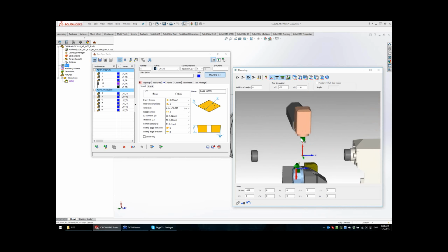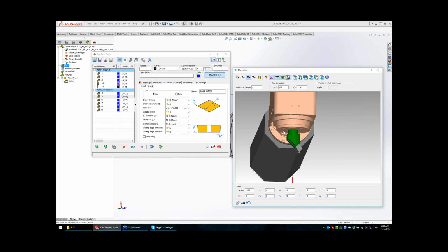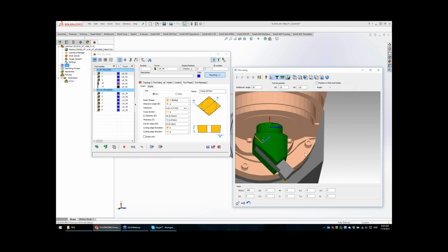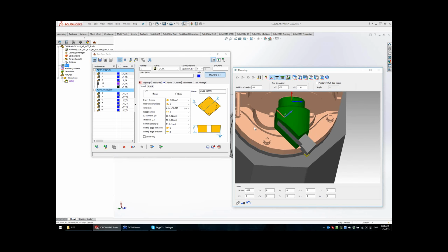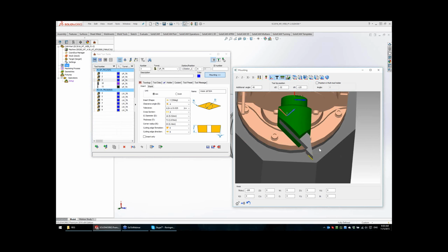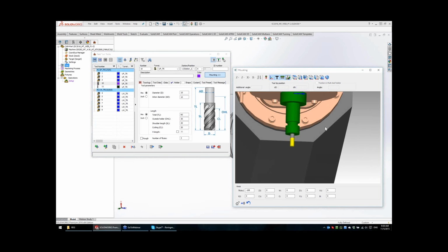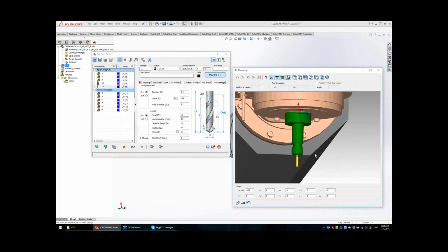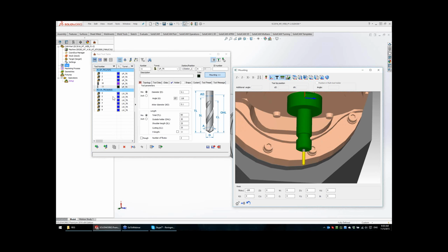So that was the tools for the lower turret. Now let's see the upper turret. I have tools on the upper turret. I can also browse them. On any click on a tool, it will be mounted on the upper turret. This tool number 1 is an 80 degrees insert. Now tool number 2 is a 55 degrees insert, then a 35 degrees insert, and I have a 10 millimeters milling tool, and a 5.1 millimeters drill tool that I will use in this part.